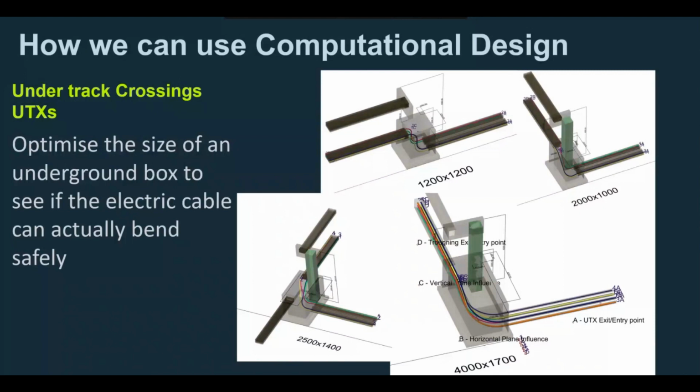And at the time in the 3D solution, MicroStation and AutoCAD could not do a 2D plan to identify the 3 or 4 degrees of bending for a pipe. But I was simple enough to use a function called fillet in Rhino, and then I could just have a solution, and I could say this fits. I could show this to the client. They would assess if it would fit, and if they're all happy, this would be the size we would use for the whole project.